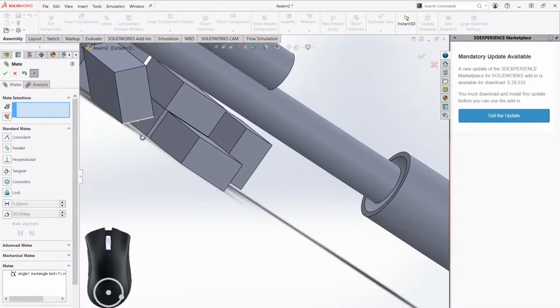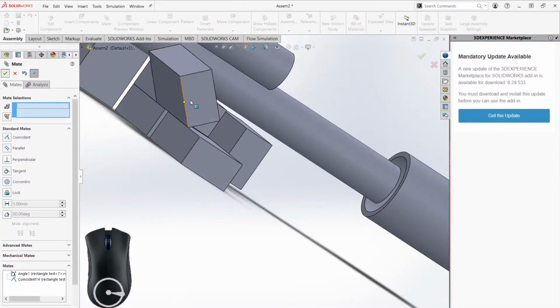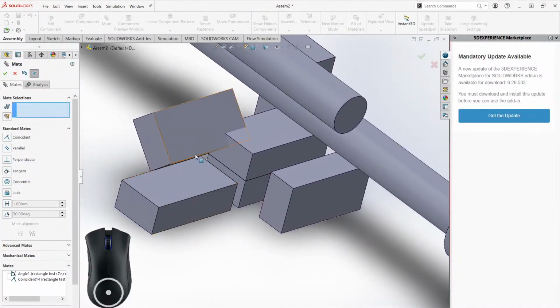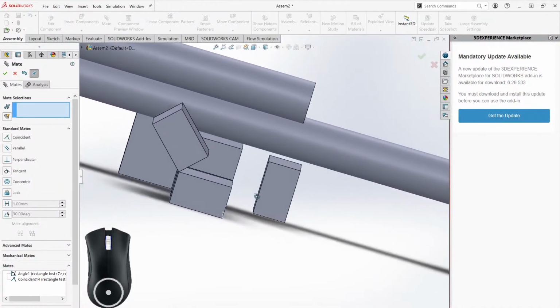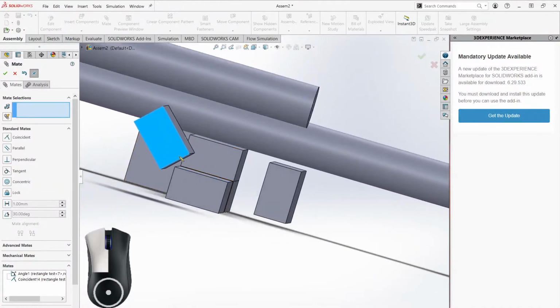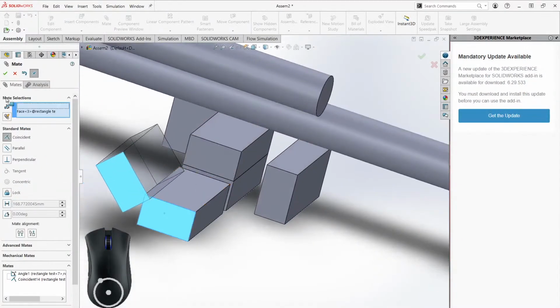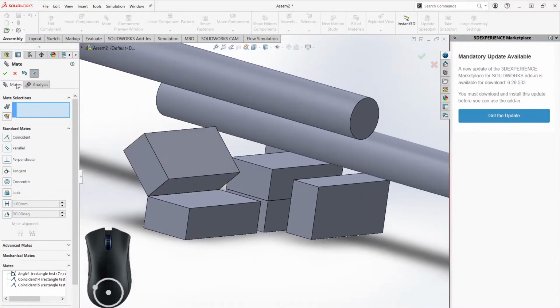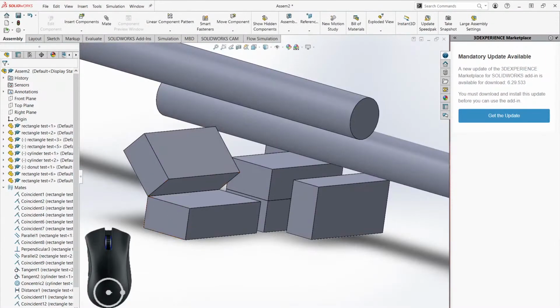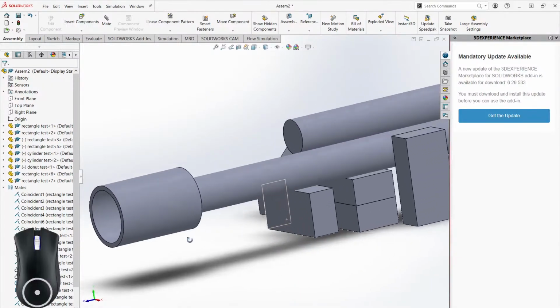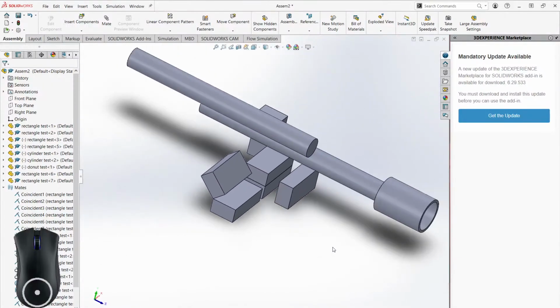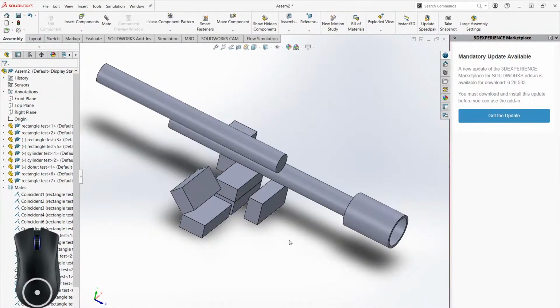So do that, and I can say that this is coincident, right? Coincident doesn't have to be just faces; it can be edges, points, or anything really. Now you can see that those two are 45 degrees apart. You could say maybe not a coincident. And there you have it. Those are the basic mates that you'll see in SolidWorks. Coincident will be your friend. Tangent and concentric are very helpful for mating screws or something into the right place.